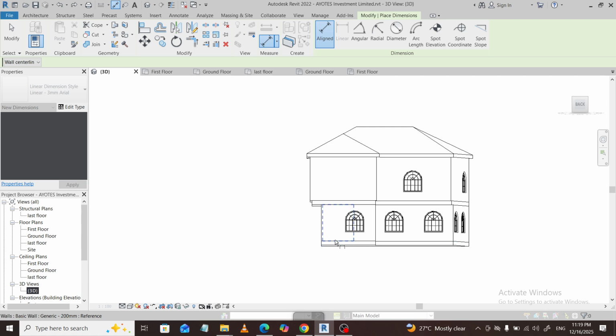This is especially helpful for things like the length of a beam, the edge of a wall, or a run of pipe. Select the tool, hover over the edge you care about, and Revit will report the length following that element's path, not just from point A to point B in space.